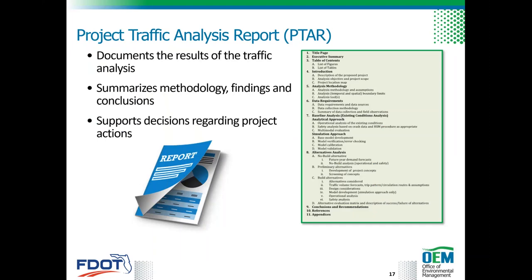Okay, so now let's talk about one of the technical reports. This is the Project Traffic Analysis Report, or PTAR for short. So the PTAR documents the assumptions, the methods, the traffic forecast, the design traffic, and the results of the traffic analysis for the project in plain language and an easily understood format. It summarizes the data collection effort, the input parameters, the traffic analysis tools, the existing conditions, the development of future traffic forecasts, and traffic operational and safety analysis of the project alternatives.